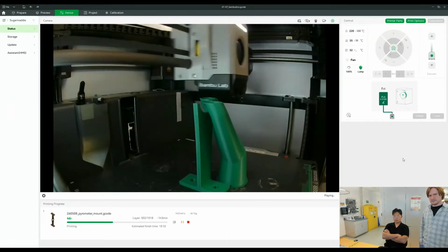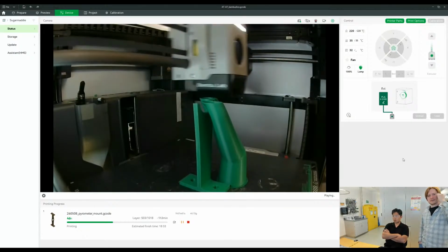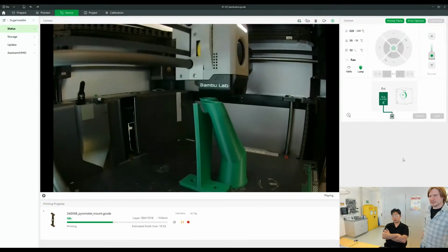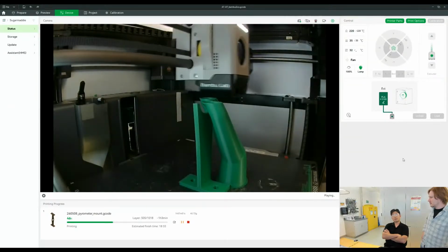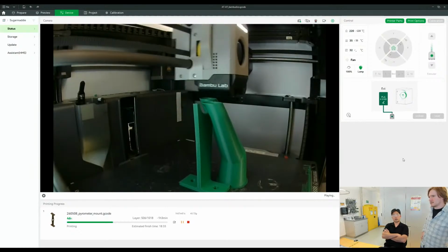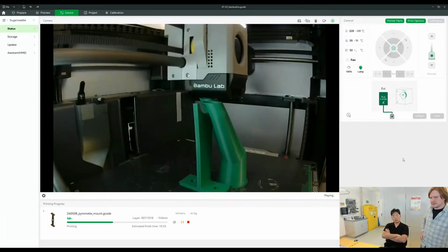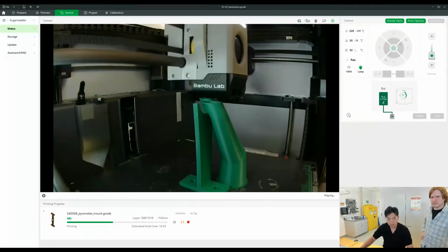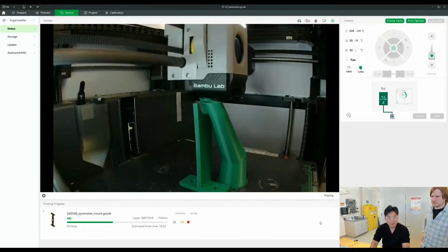If the current lines up, right, you might need like the 50 amp version. I don't even know what the AC power requirement would be for our setup. We'd have to figure it out. Yeah. I mean, it'll be a little bit more than if you're using DC because it's not quite as efficient at heating. Yeah, but ultimately, don't you just have to take the area under the curve for an AC curve, right? It's just like the RMS. Yeah. If we calculate it based on the VRMS, then we should be getting a similar idea, right? Yeah, it'll be a little bit less than if you had the same voltage and current with DC.